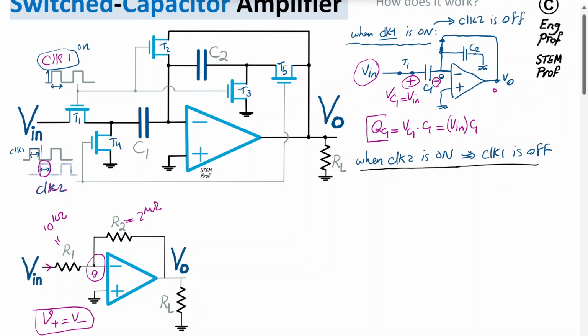Okay, so the circuit looks like this now. We have the T1 switch off, like a completely open circuit as an ideal switch, T2 off like an open circuit again, T3 off like an open circuit. So the only two transistors as switches that are on, with an ideal switch, would be T4 and T5 that are shown here.